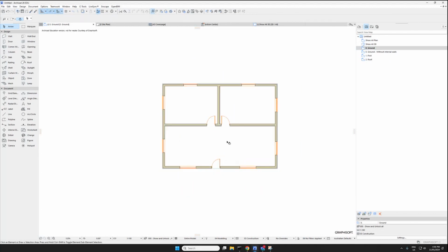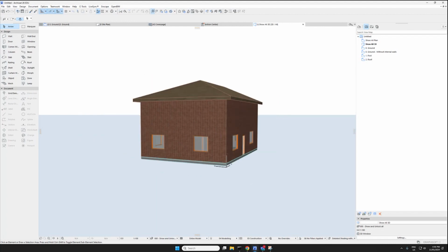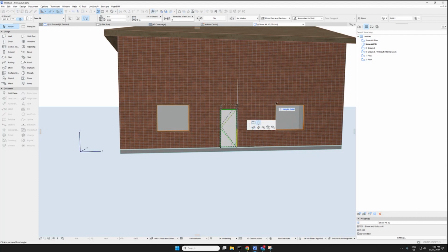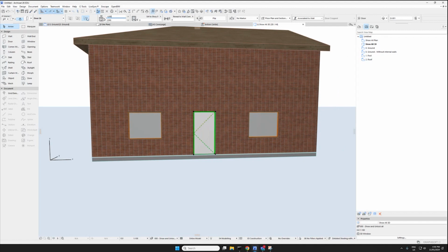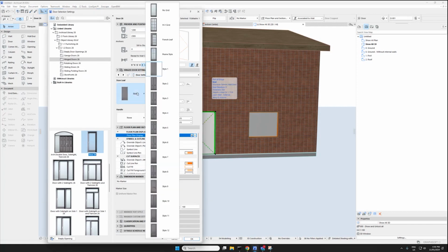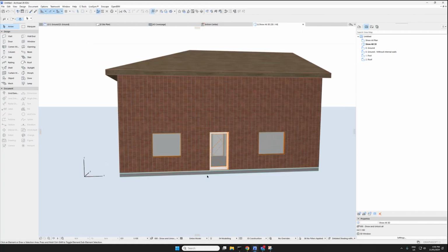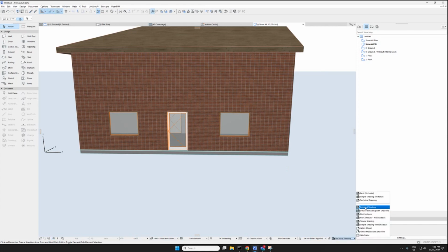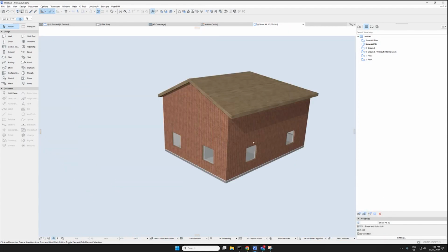There you go. All right, so we've got that, and we go into 3D view. We can see that's been done, and we might want to change this so it lines up with the height of the windows. So I've just clicked here, clicked on the node, and clicked on this one, which is stretch vertically, or you can stretch it horizontally. I want to stretch it to line it up with the windows. You might want to beef this one up to 1200. That's it. And then we can change this, inside here, door setting, door leaf. Might want to be a glass door. It looks a little bit funny now, but we can change this to be down here. We can go into no contours. It usually looks a little bit better.